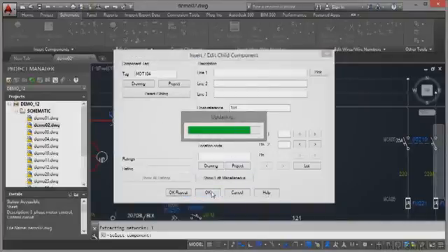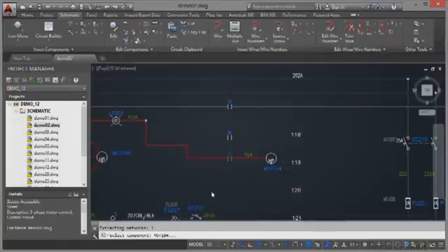So when I click on OK now, everything will update in the project. Takes a few seconds, and you'll see there MOT 104, 104, 104, 104. So there's the parent object, which in this case the component is the motor, and then the motor contacts that start up the motor are related back to that as the child. So these are now linked in the database in the AutoCAD Electrical project as a parent and a child. So you can link these things together so that when this is being installed as an installation, people know what links to what in your AutoCAD Electrical drawings.